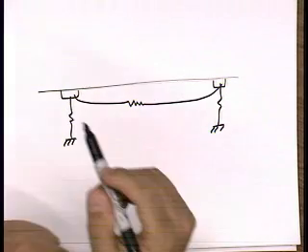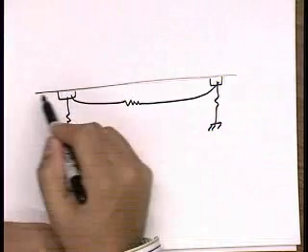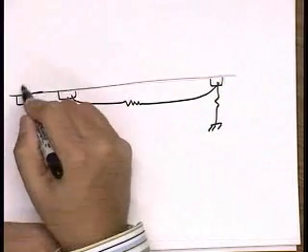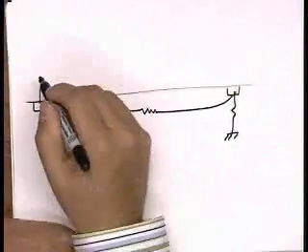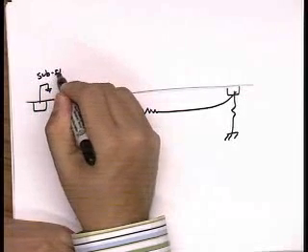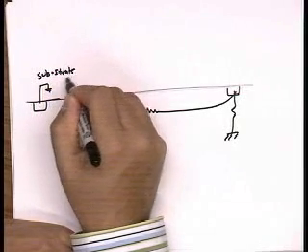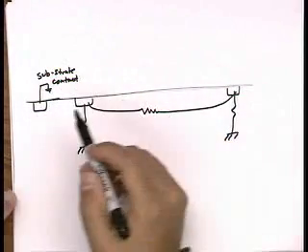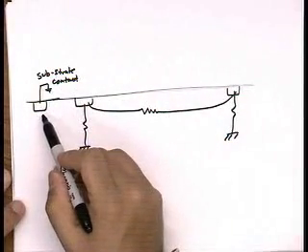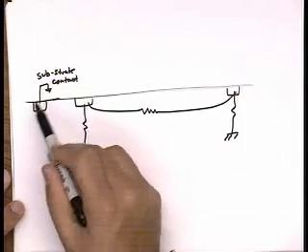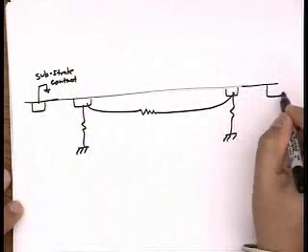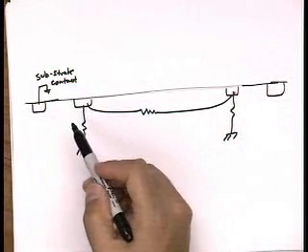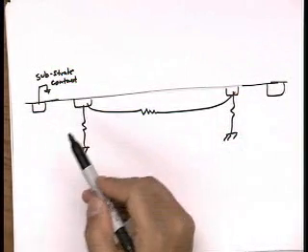Oh, okay, I cheated a little bit. I didn't show you the whole picture. Well, you know that there's always ground contacts at the surface, right? This is what we call a substrate contact, or a substrate tap, right? So either advertently or inadvertently, we are going to place several contacts like this around our chip, right? Anytime we lay out a transistor, we do this, right?